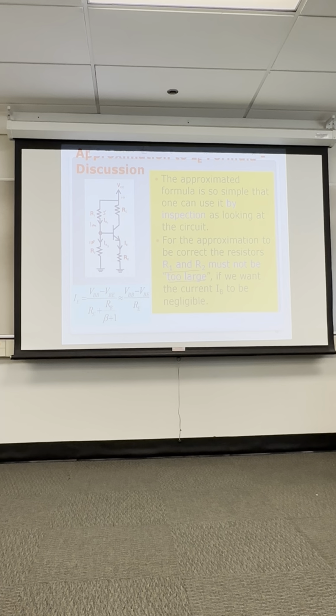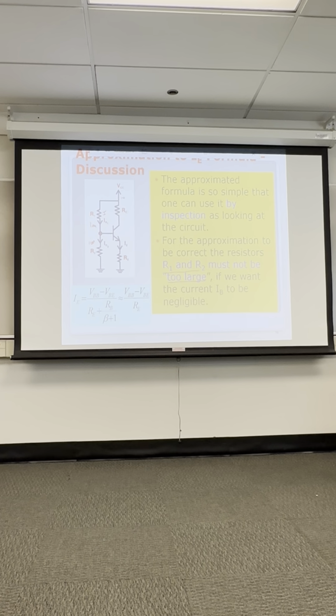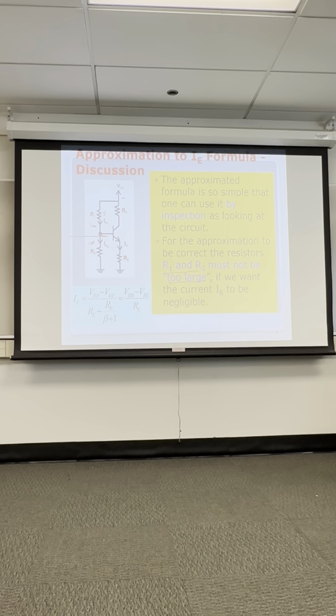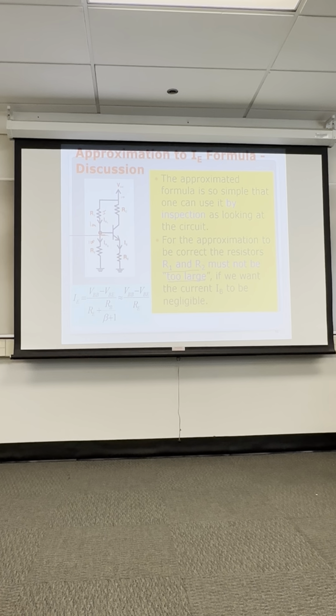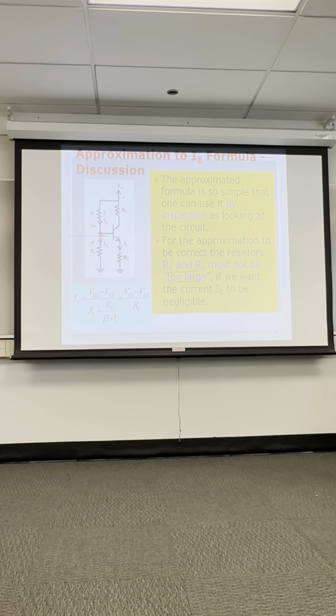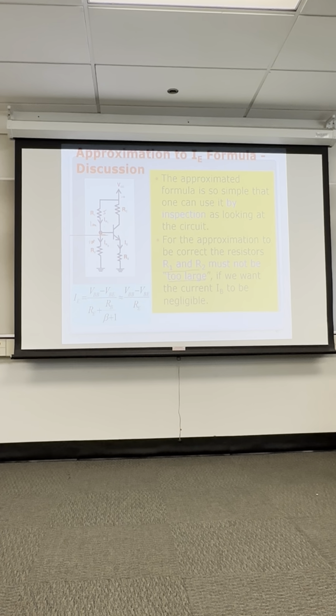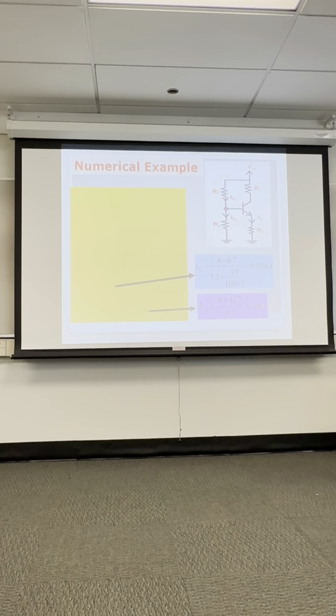It says from the battery there's only 500 nanoamperes of current available, and resistor R2 will take some of that current. Overall, it means there's no current left for the base current I sub B. So the circuit would not work because there's not enough current in the voltage divider to drive the base segment. So that's what we say. You don't want to make those two resistors too large. 10 meg ohm is way too large. These resistors are probably under 200K or even under 100K, depending on the current in the transistor.